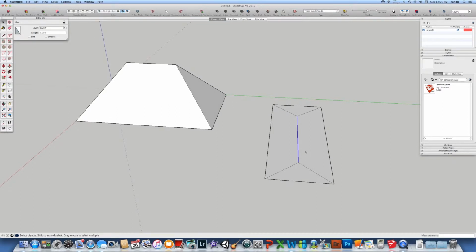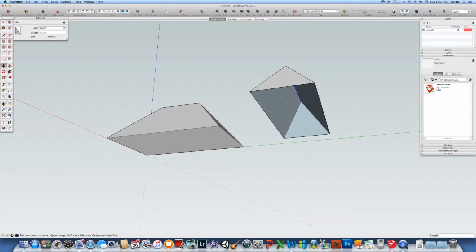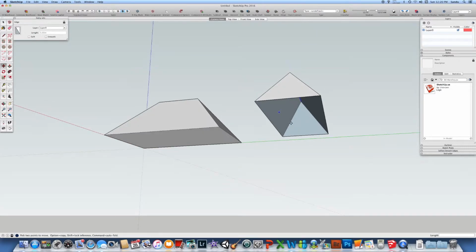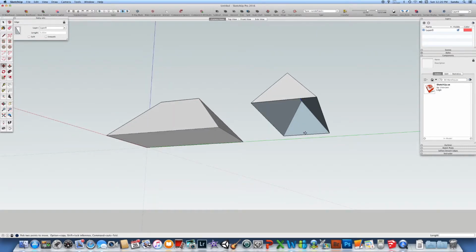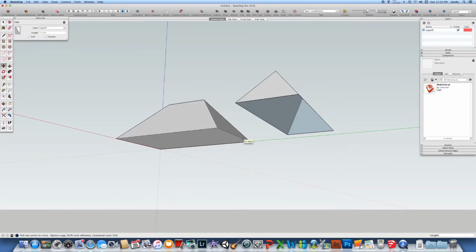So I just want to make you notice something. Each time you move on the vertical, let's say we move this by 2 meters, notice when you move the line, on the bottom you're not going to have an enclosed volume. So I always build a rectangle on the bottom, and in this case you press R and you build a rectangle.